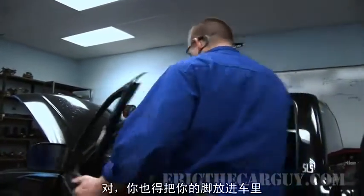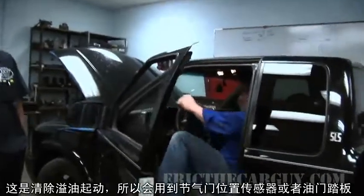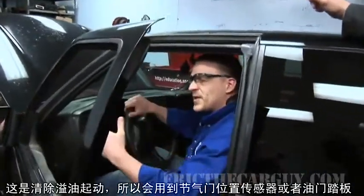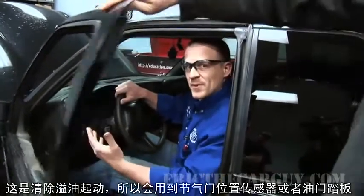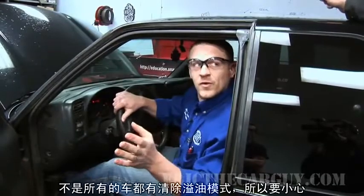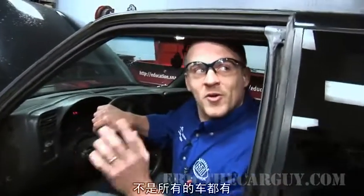And you're also going to put your foot to the floor all the way on the gas. This would be a clear flood crank, so it would be TPS, that's throttle position sensor, or gas pedal, all the way to the floor. And not all cars have clear flood mode. Be careful. Funny story on that. Okay. I thought they did. Not all cars have it.